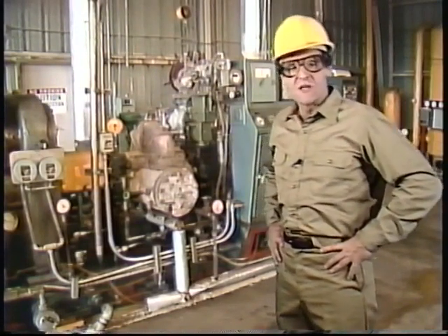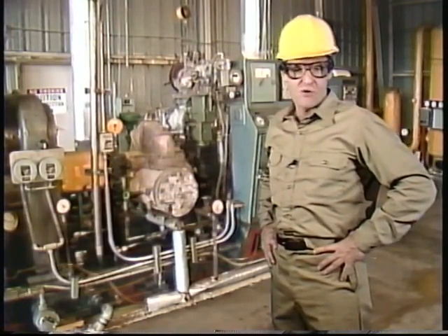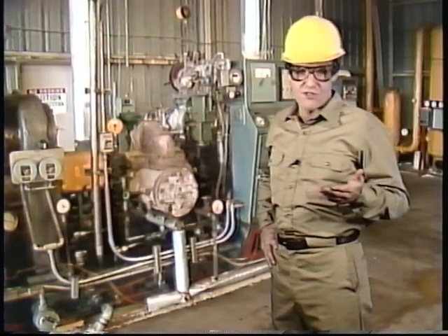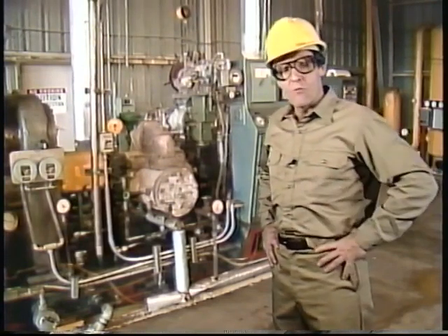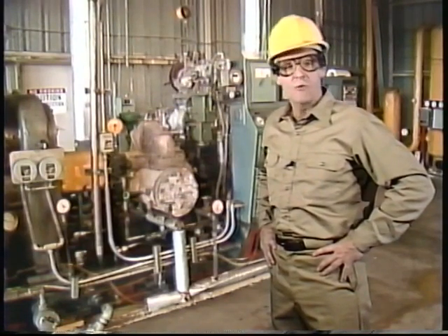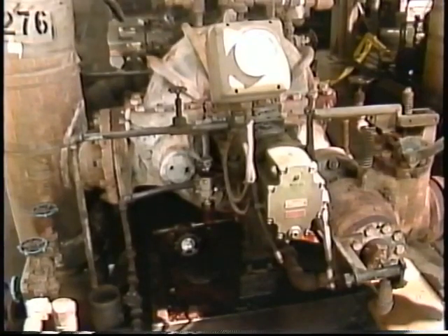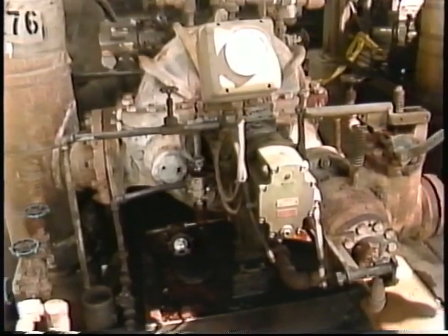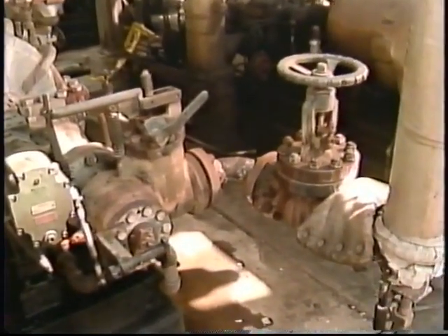To handle this responsibility, you must know what auxiliaries are used on the turbines in your facility and what these support systems are supposed to do. So, in this part of the program, we'll take a look at some common turbine auxiliaries. We'll start with valves. A turbine typically has an isolation or block valve in the steam supply line. You may hear this valve referred to as a throttle valve.